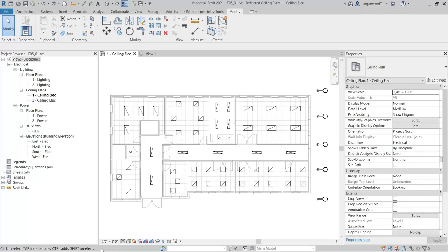When adding any electrical connector, it's important to ensure its values are aligned with the values set in the electrical settings to ensure correct and valid connection within the project. We will review the electrical settings in this project, then from within the Family Editor, add an electrical connector and apply the appropriate values. The light source for the lighting fixture will also be reviewed, along with the application of photometric data.